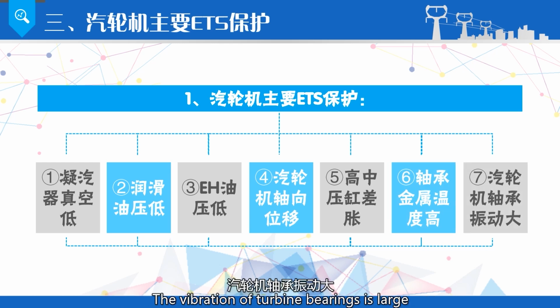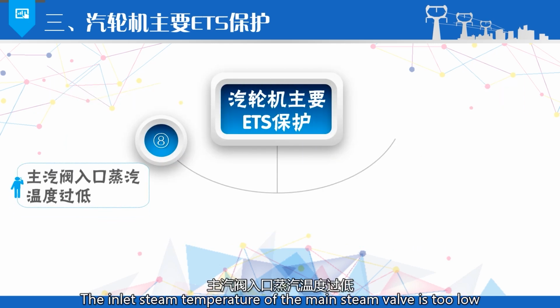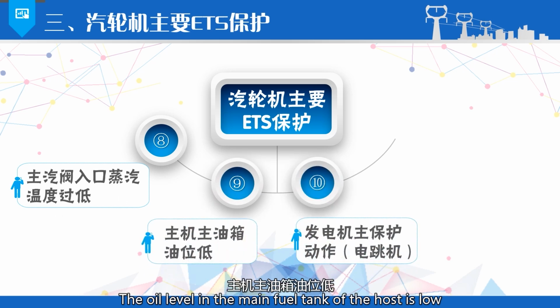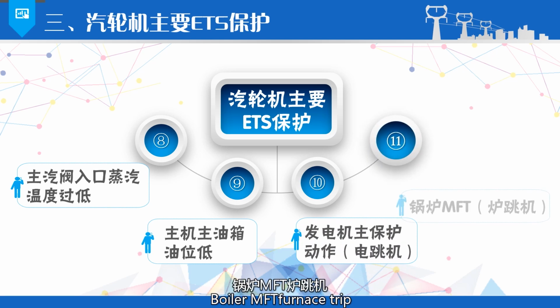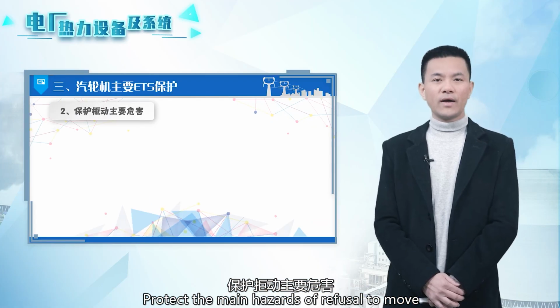The vibration of turbine bearings is large. The inlet steam temperature of the main steam valve is too low. The oil level in the main oil tank is low. Generator protection action, electric trip. Boiler MFT, furnace trip. The main hazards of protection refusing to act.